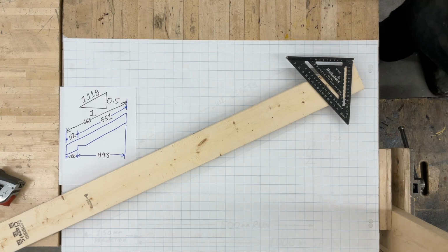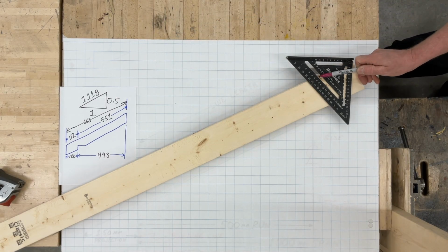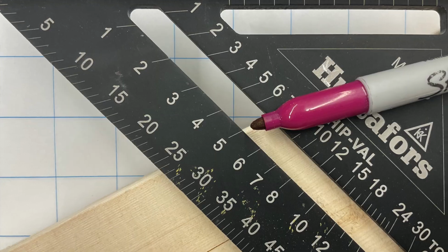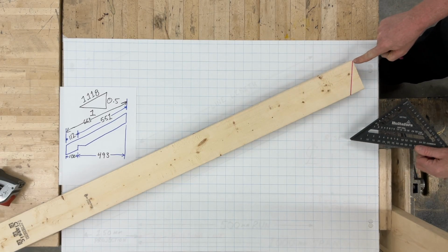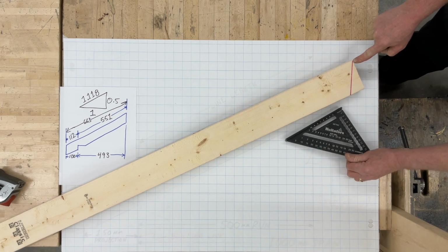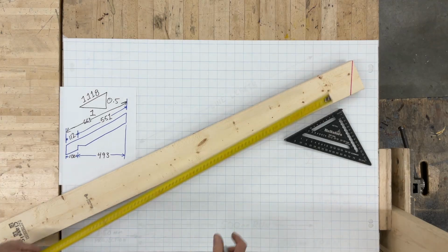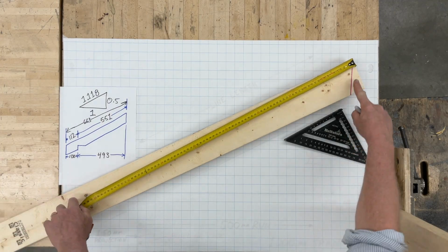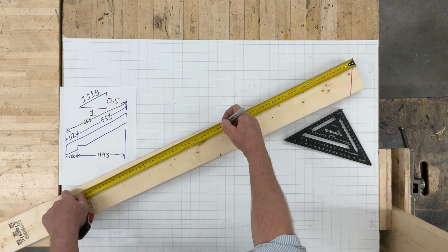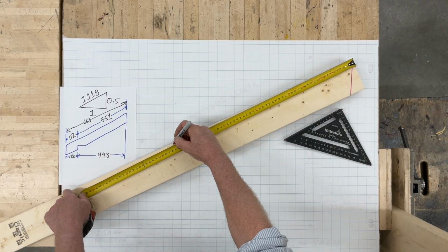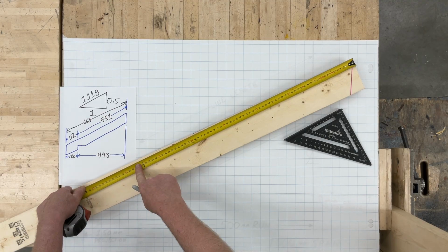Now let's lay out this rafter. A tangent of 0.5 equates to the 50% or 5 mark on your metric speed square. After sighting your stock for crown, mark the plumb cut of the ridge right at the top corner of the rafter so that you can hook a tape on the end and pull all of your measurements from that single point. Then, mark your adjusted line lengths right on the top corner of the rafter stock. If you don't mark them on the top corner, your lines will not be in the correct locations.